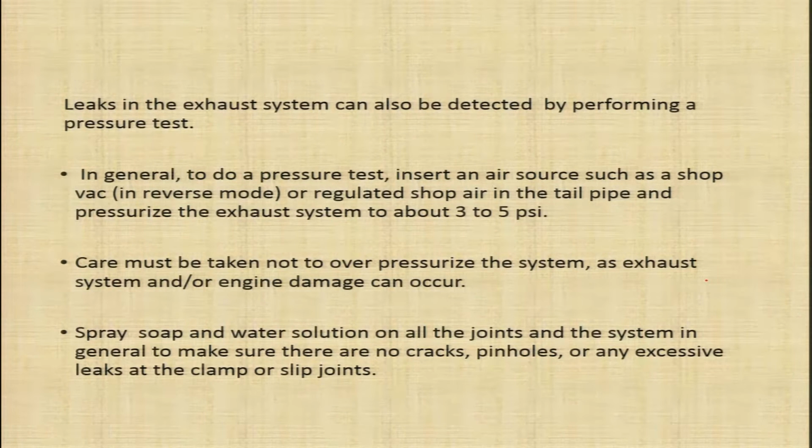Spray soap and water solution on all the joints and the system in general to make sure there are no cracks, pinholes or excessive leaks at the clamps or slip joints.